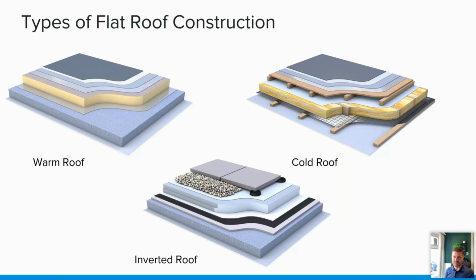An inverted roof is fairly obvious. When you step on the roof, you're going to see paving slabs, you're going to see ballast and things like that. I wouldn't recommend core sampling these roofs if we don't have to. They are usually over a concrete deck, and we can usually establish that from inside the building before we step on the roof. So they're the three areas.